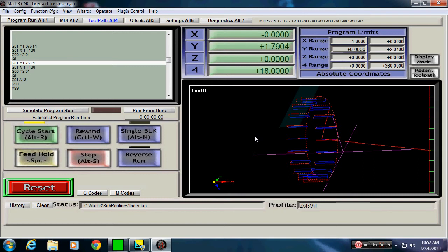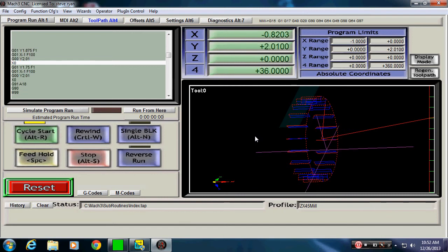When I was saying I cut the profile into a disc for the tooth profile and make the involute gear cutter, then you can use this same software to separate that into, say, 6, 8, 10, whatever cutting teeth in it, and come in from the top, like a spline would be cut, and offset it and rotate it at a 7-degree angle and cut each one of the teeth and make your involute gear cutter.